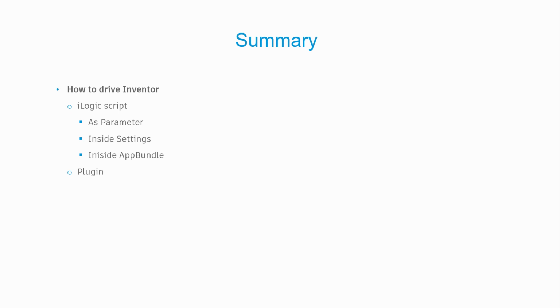Plugins. Code which you can write using Visual Studio and debug locally before deploying to Design Automation inside a bundle. Dealing with assemblies inside the zip packages. The zip package is automatically unzipped, then processed using your code and automatically zipped before sending the result. You can use the ability to zip whatever folder you like. So if you have some activity which produces multiple files, you would like to zip and send them in one package, you can just save them in one folder and mark the output parameter as to be zipped.